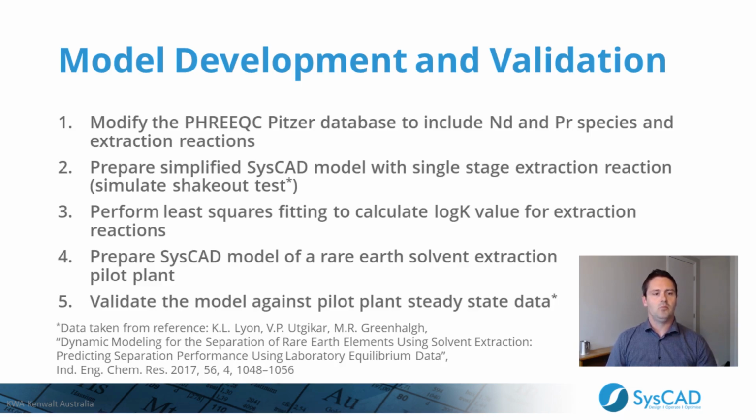We then prepared a SysCAD model with a single extraction reaction to simulate the shakeout test. Following this, we did a least squares fit to calculate the log K value for each reaction. And after this, we prepared a SysCAD model for a rare earth solvent extraction pilot plant and validated the model against the pilot plant.